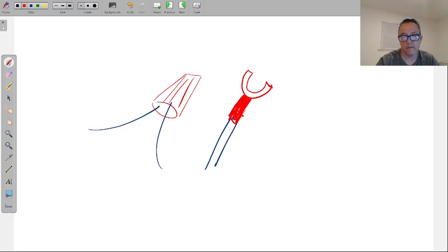All of these things that bring two wires together or join wires to a termination point have to have a temperature rating, a heat rating, that is the same as the wire's heat rating for the insulation wrapped around the wire. All right, now we'll just let that fact be a fact, and now we're going to jump over to the table that I had mentioned.